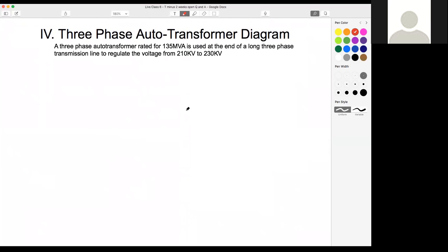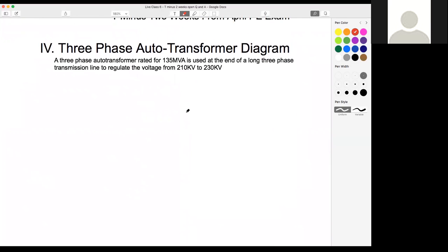Carlos said, do we see this type of problem for VFDs? Yep. Thyristors, same as an SCR or a silicon controlled rectifier, are the switches in a VFD that cause those pulses. Because remember, a VFD is essentially like an inverter, and it controls the speed by controlling the frequency. Remember that equation with poles and frequency to get speed in our motor chapter? So a VFD is going to be changing the frequency.